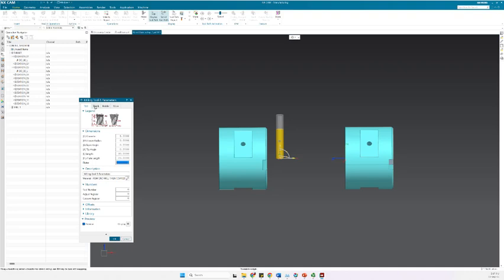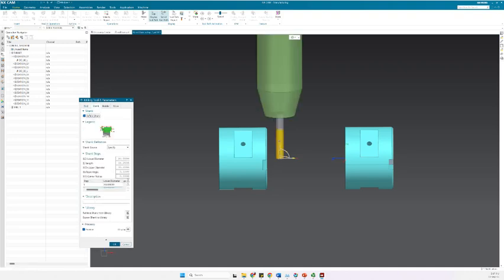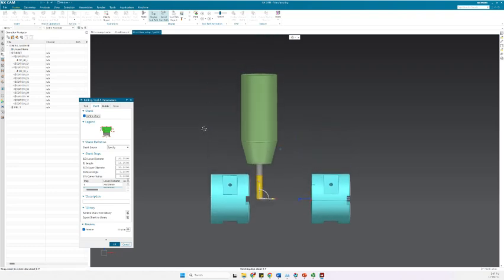Of course, the end mill is connected to the shank, and this is something that you need to either decide here, or see what the shanks are that are available in the workshop, or what shanks are used in the workshop by your operator. It's better to define exactly that one so that you can make sure there wouldn't be any unwanted collision.